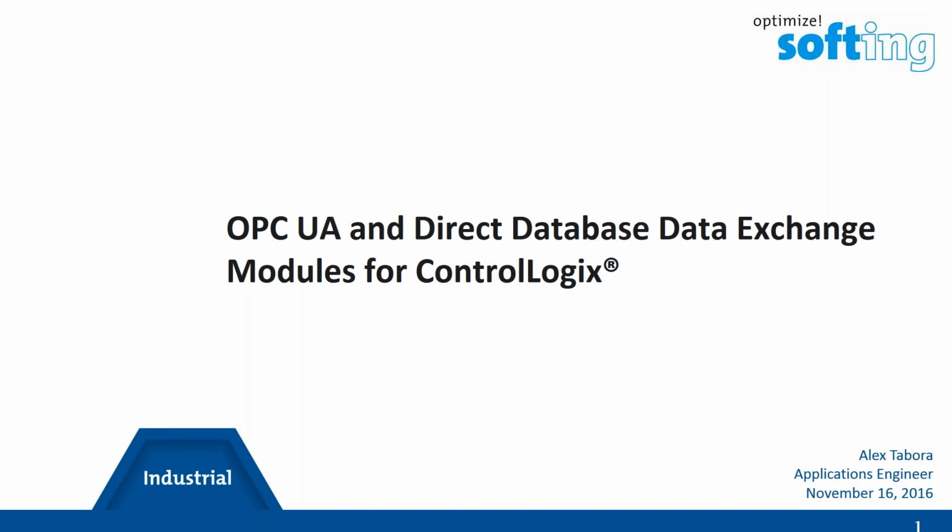So can the OPC UA module also be a client? No, only server. Can it be a server and a client? No, only a server. So that would answer that first question of whether it can replace a produce consume network. That would be no, because you need client and server to do produce consume. Okay, I misunderstood the question.